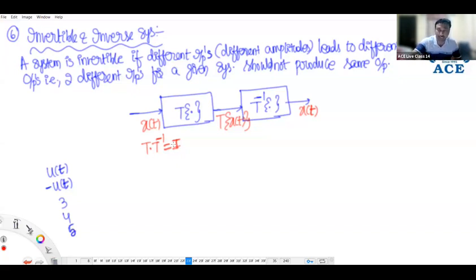In communication, we study different forms of equalizers, to avoid ISI, intersymbol interference: raised cosine filter, zero forcing equalizer. So whatever distortion is introduced in the channel, to undo that effect we design an inverse block, which is called an equalization technique.